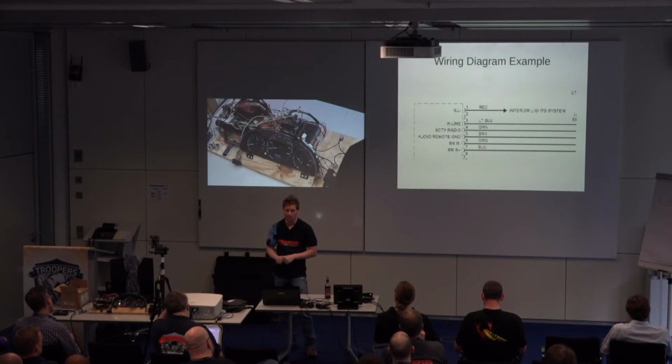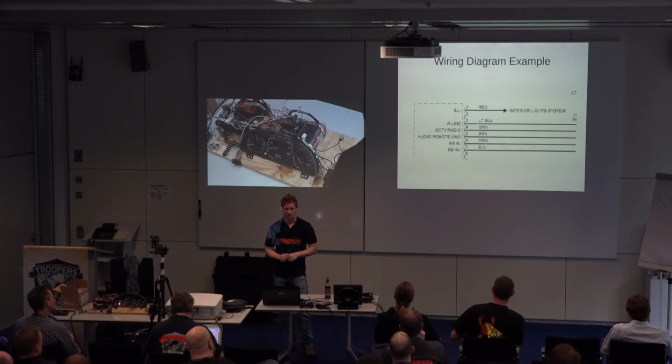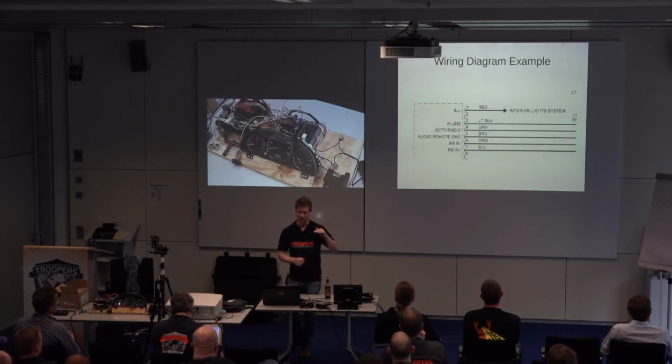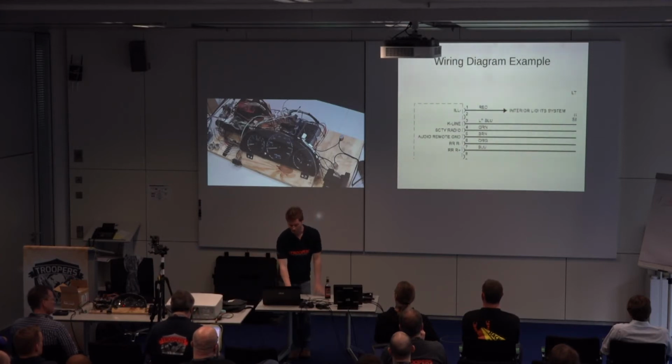But I've noticed also when you're doing this type of research, don't take for granted that the bus you're on is the only thing you can do. So if there's a high-speed bus and say it does braking or acceleration, and this is, say, a low speed that's typically only connected to maybe the door unlock, if you know the protocol to send, I've only really seen this on CAN, from CAN to CAN, low speed to high speed CAN. You can send it on, say, a high-speed signal and a low-speed signal, and because they both go into the same ECU unit, it just handles it anyway. It shouldn't be on there, but it works just fine. So you should definitely try it when doing audits.